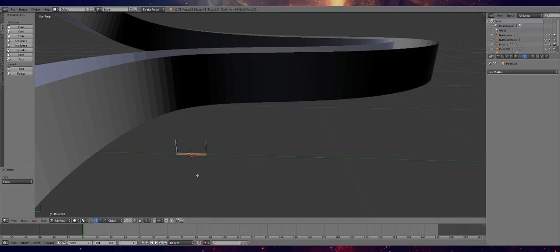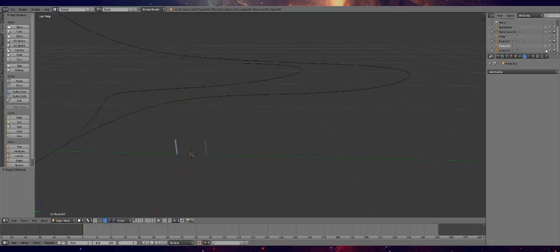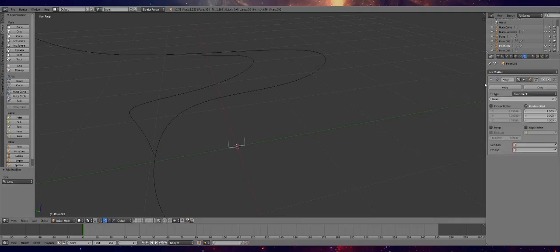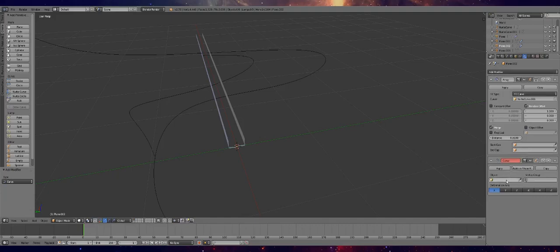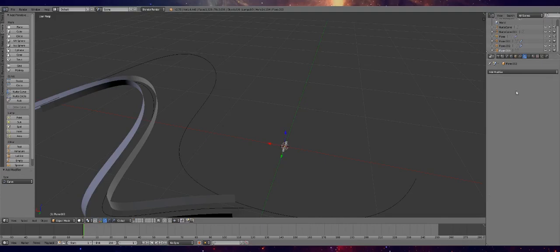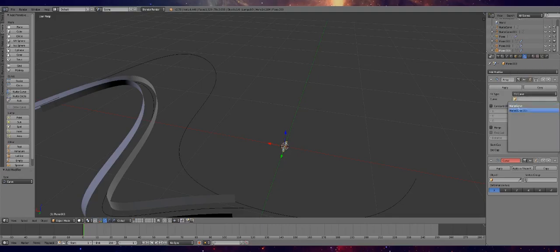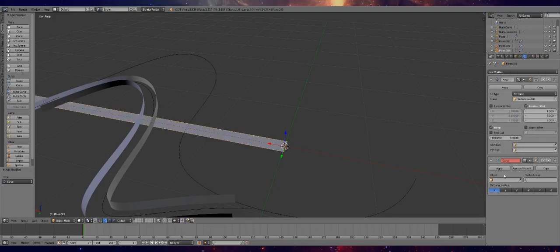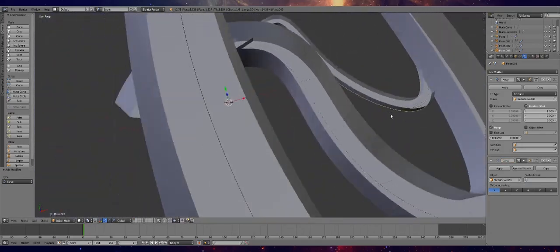Let's finish off with that phase. Now we have two new objects. There are new walls and floors. I'm gonna hide the other two because we don't want to see them right now. And I'm gonna do the same treatment. I'm gonna add array, go fit curve, select my new curve, click merge, go to a curve modifier and select my new NURBS curve, and hey, that's my new path, right? Looks pretty good. Let's go to the other one, array, curve, fit curve, no, sorry, not constant after that, merge, and boom. Now if you show both curves, you can see we have some problems.